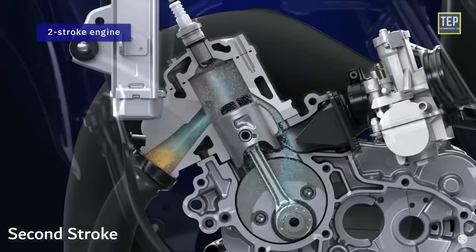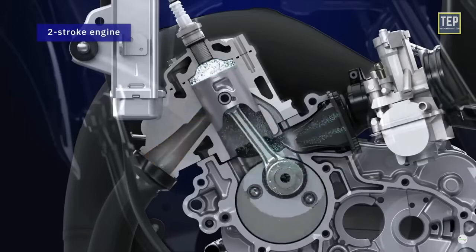The expanded gases start escaping through the exhaust port, and at the same time the fresh charge, which is already compressed in the crankcase, is forced into the cylinder through the transfer port. The charge strikes the deflector on the piston crown, rises to the top of the cylinder and pushes out most of the exhaust gases. The cycle of events is then repeated.